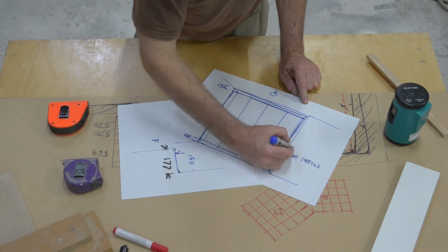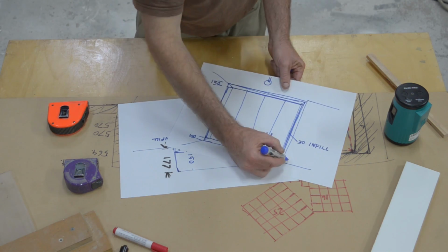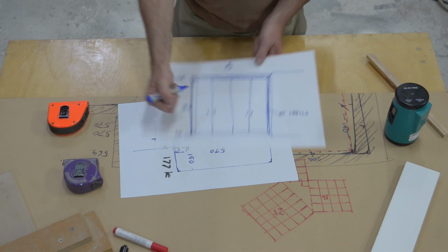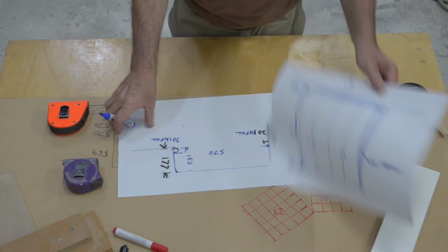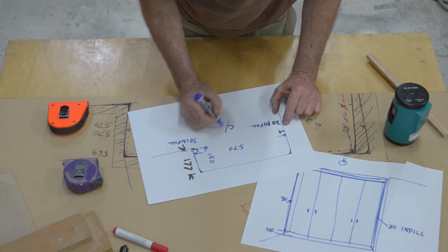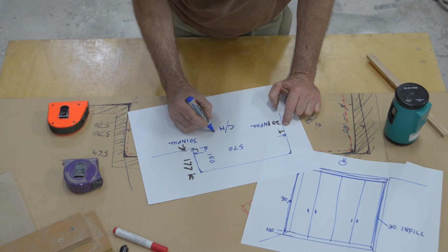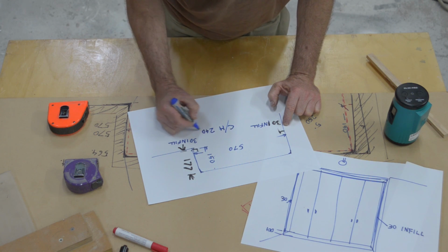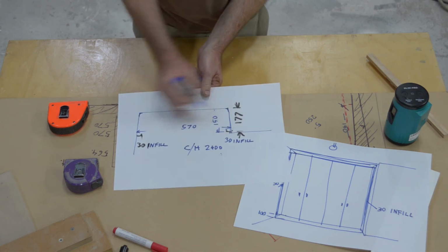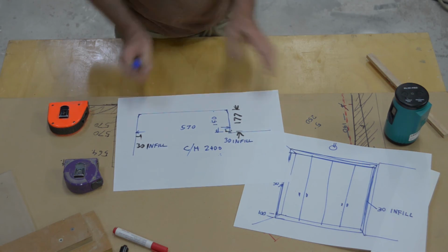And the height, I might mark the dimensions this way on the drawing, depending on what I needed to do. But if I've got the information here, that's fine. What I would tend to do is put the ceiling height, 2400 or whatever the height would be. And I might also measure the height in a few places, depending on what I see on the site.